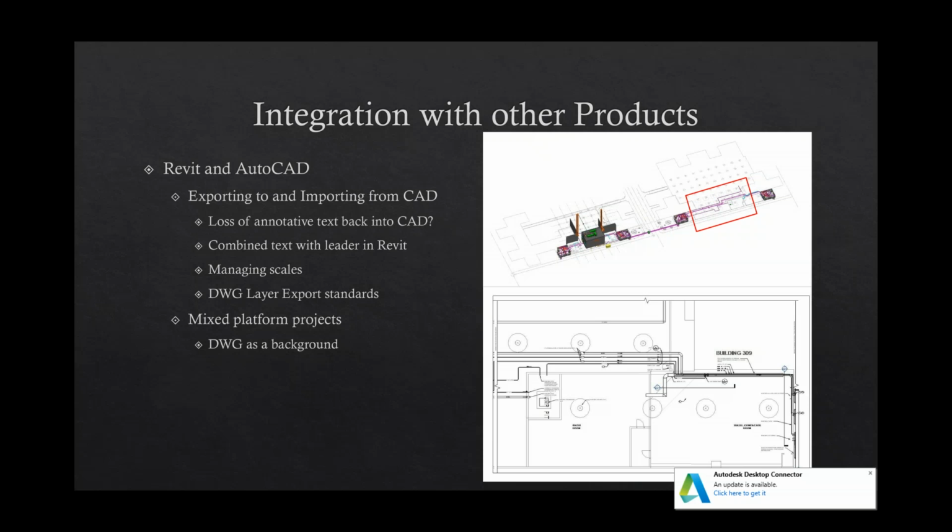So here's an example from a CHP project where we had a long, full AutoCAD background for usage. But since it was boilers, we knew we wanted to have things in 3D because it was going to be very complicated. So we ended up doing some modeling of the architectural ourselves, as you can see. And then the background we had loaded, again, I always advocate, if you're loading in a CAD file, load it per view only if you're doing a usual 3D model, because otherwise it's going to show up everywhere.